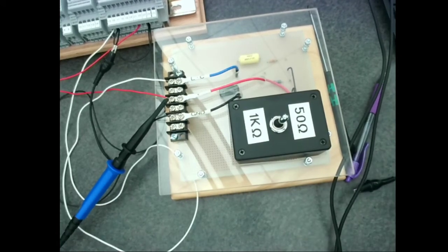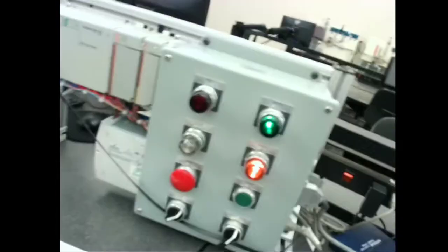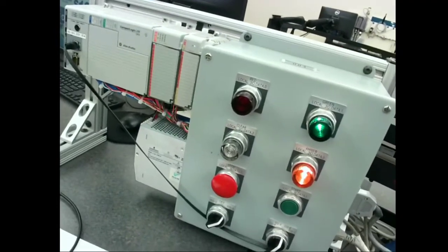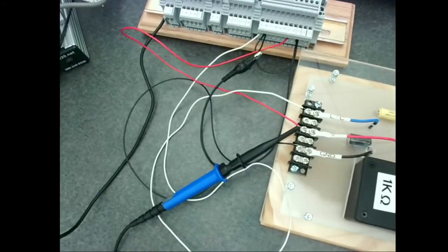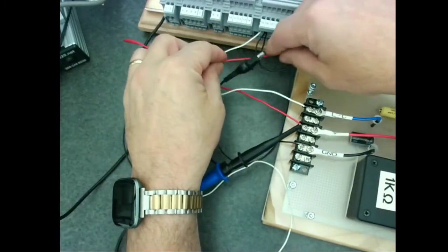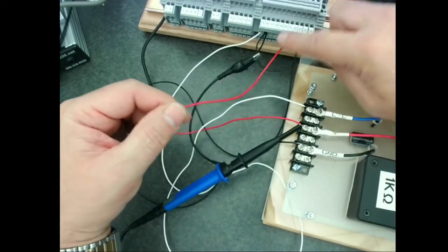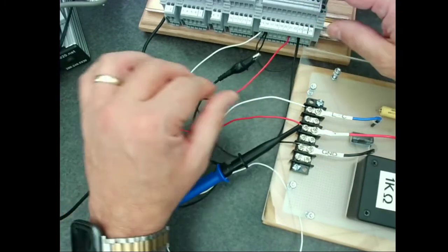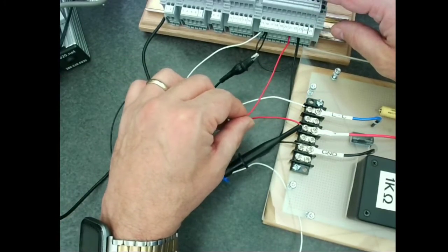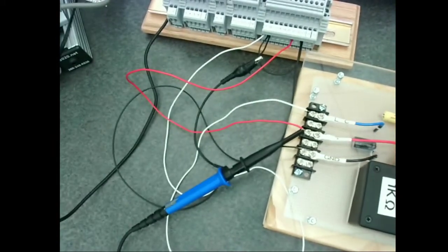And I've got this connected up here to a standard compact logic PLC with some lights and switches already pre-wired to it. We have this terminal block here, so it's wired in. So we're going to use an analog voltage out. We're coming out of pin 21 of the terminal block, which is channel 0 output of the analog output, and we're going to be feeding that in to the input of our RLC circuit.